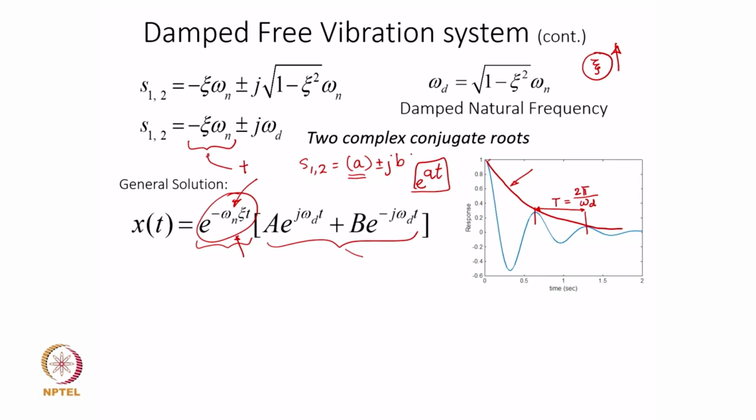it may happen, although this is a relatively rare phenomenon. There is no chance that you will always get your systems to exhibit a negative real part, but in some cases, one or two of which we might discuss in future, you may have an exponent with the real quantity in the root as positive, and that creates an exponentially increasing amplitude, which essentially means that the system is not a stable one, but an unstable one.